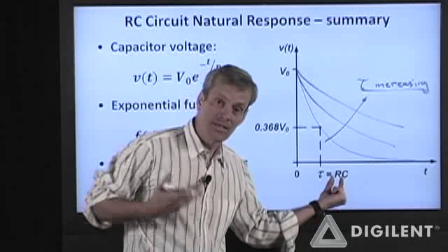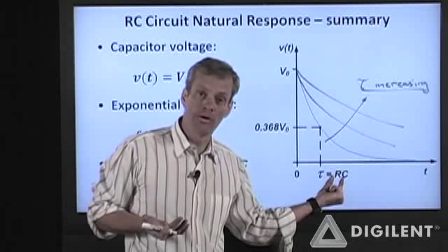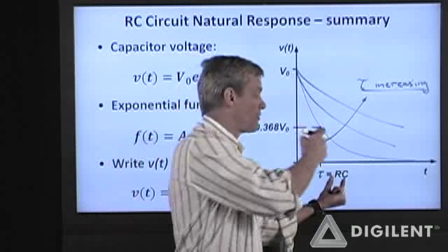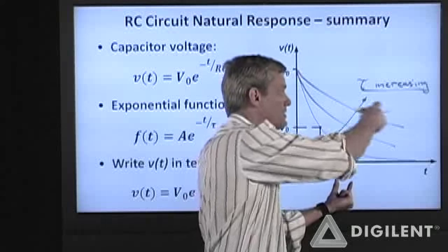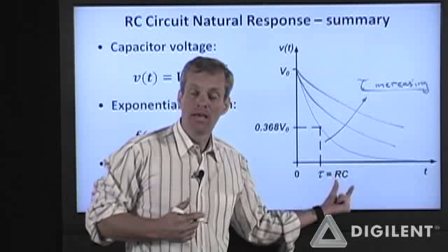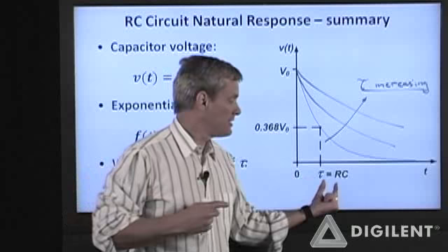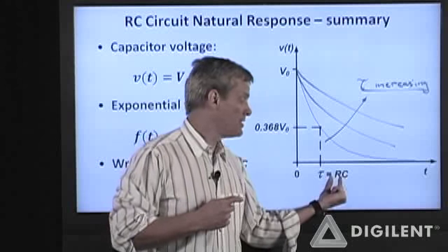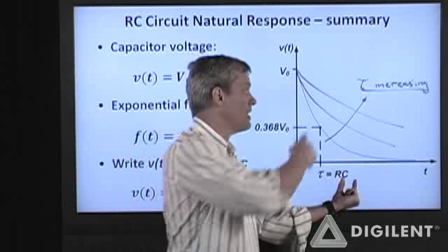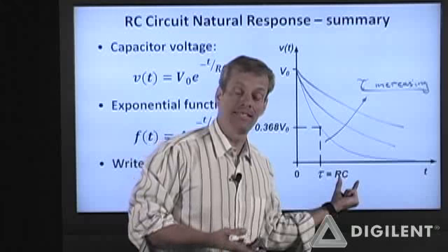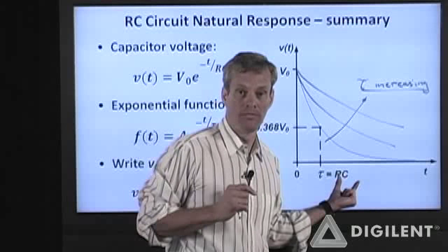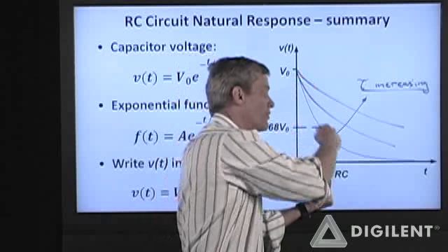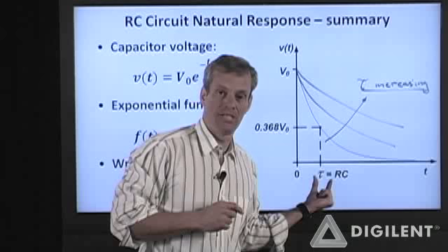Likewise, as the resistance goes up, the less current I'm flowing through the resistor, which dissipates energy more slowly. So if the resistance goes up without changing the capacitance, the time constant increases. If I change resistance and capacitance inversely to one another, I don't change the time constant at all. If I double my resistance and halve my capacitance, this response looks exactly the same as it would have done before. Okay, so keep in mind the resistance and the capacitance together are dictating the rate at which the natural response will decay.